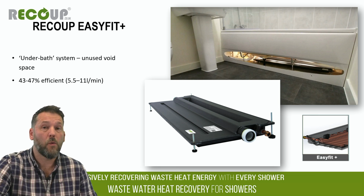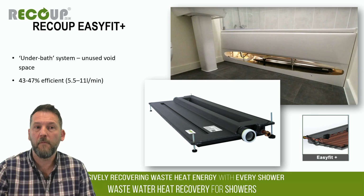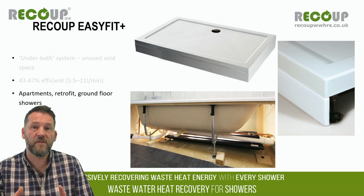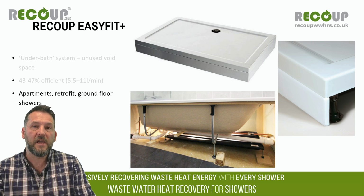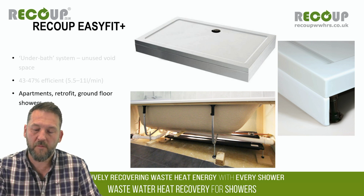By design, not quite as efficient as the vertical pipe system, which is why we normally try and specify the pipe where possible, but it costs relatively similarly, and certainly in apartments it can score similarly in SAP as well, just due to the way that SAP calculates hot water use in apartments versus houses. So certainly a good primary option for apartments with, for instance, thermostatic mixer showers over baths as their primary shower. So that's a good option there.